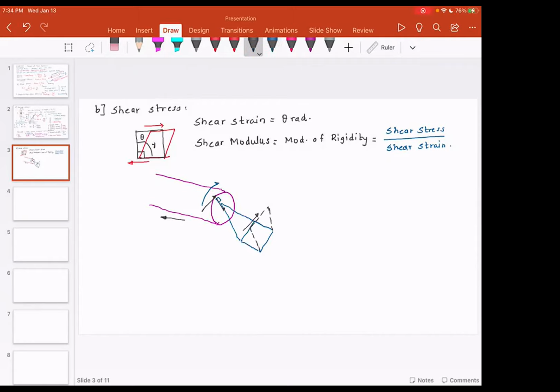Now, there is something very interesting about shear stress. I want you to visualize this block that I have shown over here, and there is a shear stress acting like this. Please understand, these two shear forces are going to give you, whether you like it or not, a moment. However, the material develops internal shear stresses that resist this movement. So you have the reactionary shear stresses in this direction, and that prevents the material from rotating.